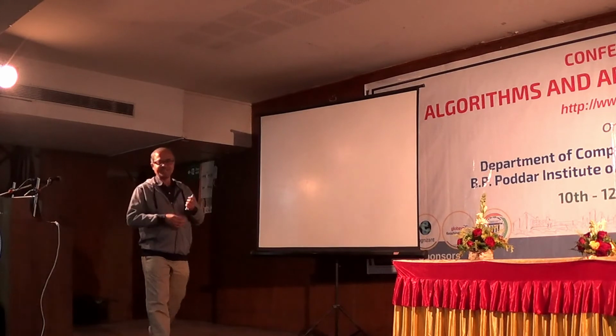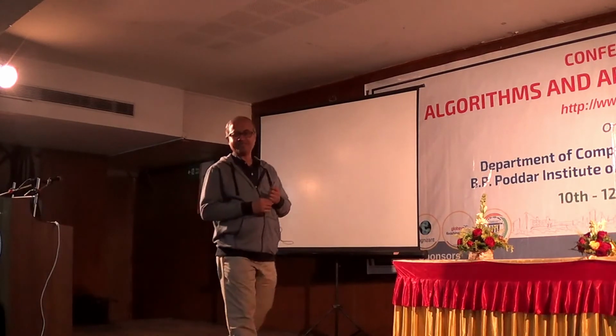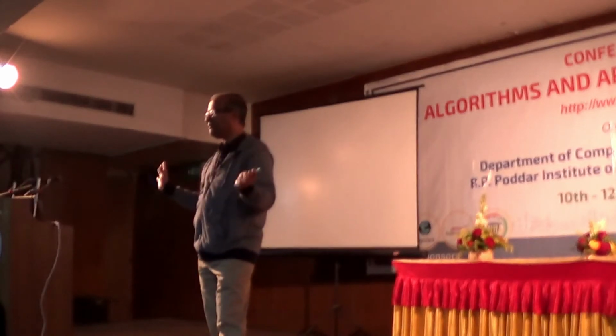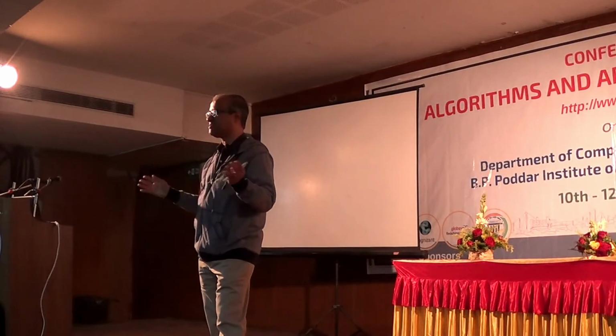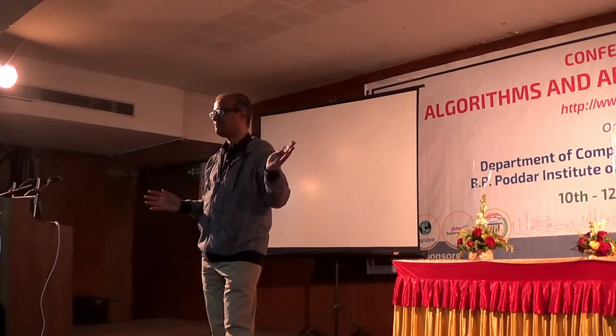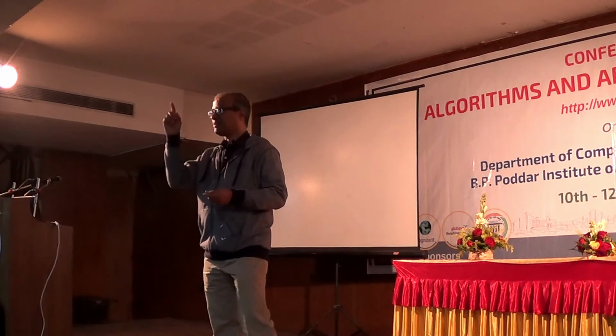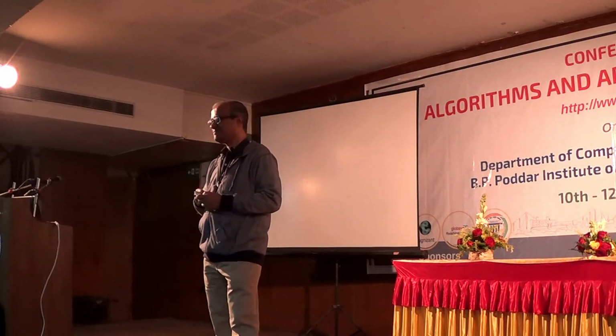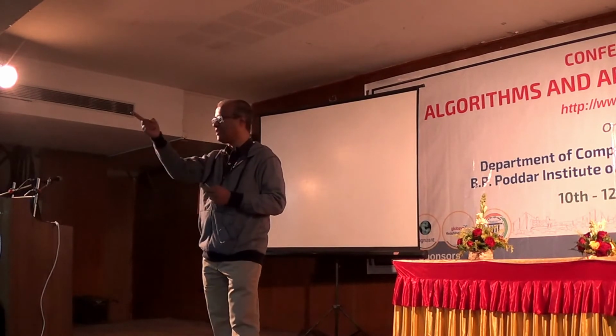Now what the sneak path problem tells us is that if you forget the environment, if you ignore the other memristors, then it seems to be quite fine. But suppose the memristor was in the 0 state, meaning you are expecting very low current to be flowing.